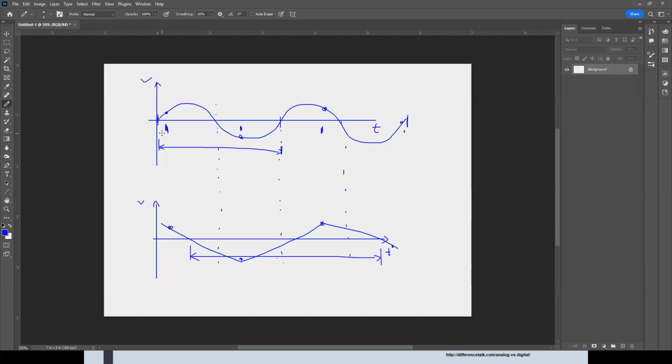So we tried to recreate that at a sample rate that is not adequate, and we ended up with something like this. Never mind the shape. However, did we at least get the same frequency when it comes to the sampling here? We did not. We have recreated a waveform that would be of some different frequency.